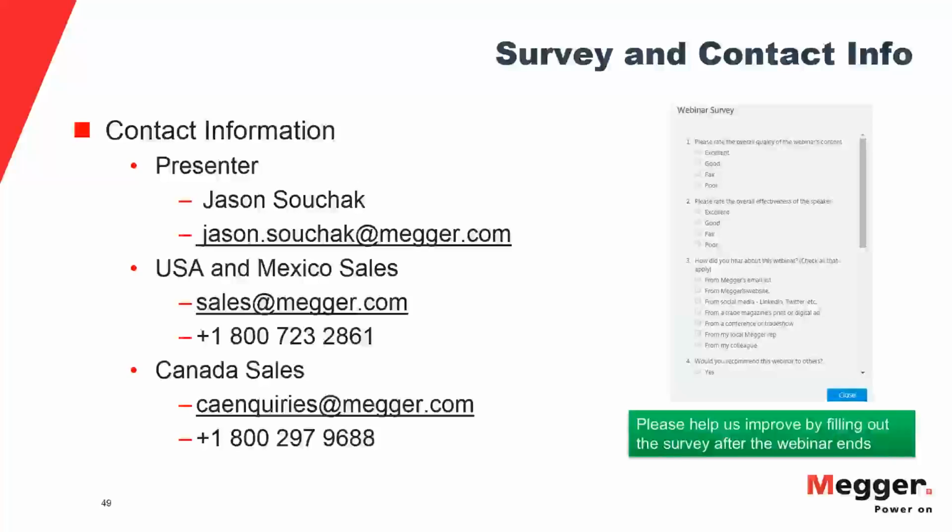Next question is for Robert. Do you have any PD, or does Megger have any PD test equipment to test 72 kV rated power cables? Part two is, do you also have any equipment for VLF testing of high voltage cables? Okay, so yes, we have equipment like that. Just to clarify, we have DAC technology for the medium voltage cables, and then there is DAC technology for the high voltage transmission cables. These systems are called DAC 200 and DAC 300, according to their output, 200 and 300 kV. We're using them quite frequently in Europe and other parts of the world on transmission cables. So that's for the DAC part.